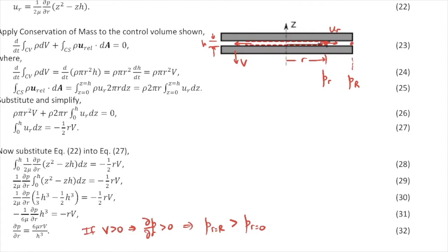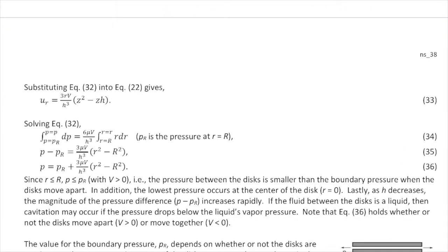And the reason I'm doing that is because I'm going to apply a boundary condition to that very end point. So that's what this derivative here is. I'm starting from the very edge of the disk and working to some arbitrary point on the interior. So here's the edge of the disk, some arbitrary point on the interior. And when you work through that math, you now get your expression for the pressure. So this is getting very close to what we ultimately want.